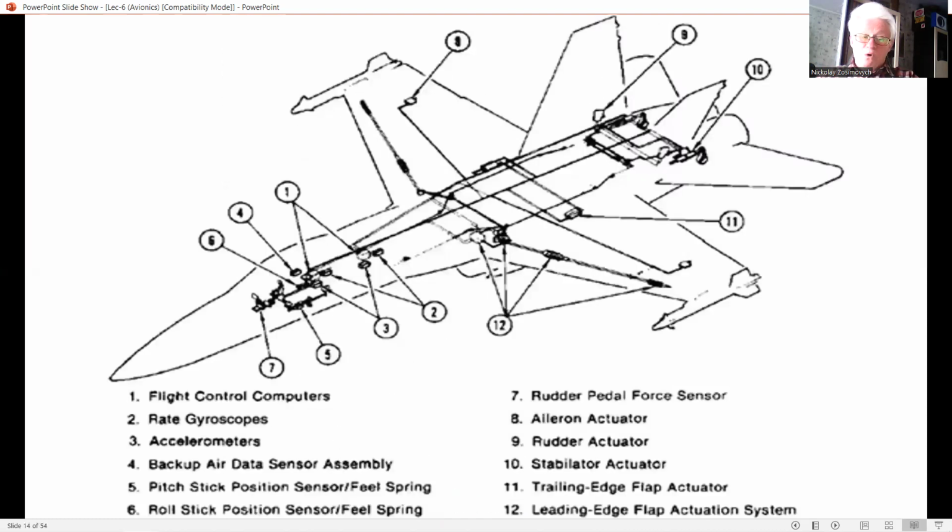The structural modes can be excited in 2 ways. First, inertially, meaning through the inertial forces resulting from the offset of the center of mass of the control surface from the hinge line. These forces are directly proportional to the angular acceleration of the control surface.